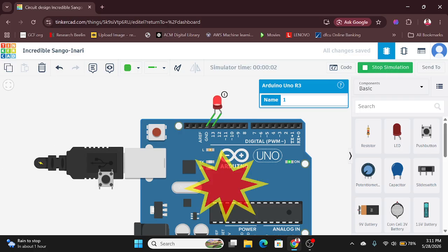You can see it is putting this red warning. Yes, the bulb is lighting. I hope you can see it is lighting red. This is the LED. It is lighting red on the LED bulb that we added. But it is lighting with this red, showing that there is some danger. And we are going to be seeing why they are sensing danger. You realize things like we need a resistor. Because there is no resistor, we are connecting direct. The LED is connecting direct to the port on the microcontroller. That is why it is showing danger.